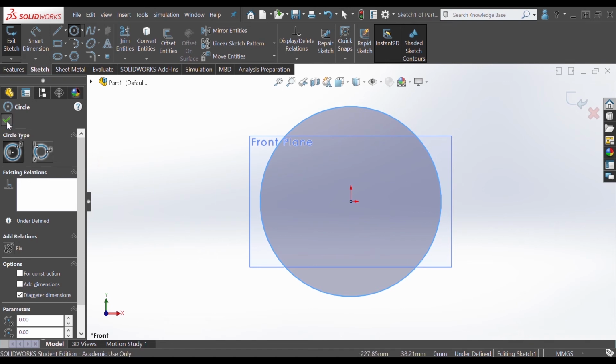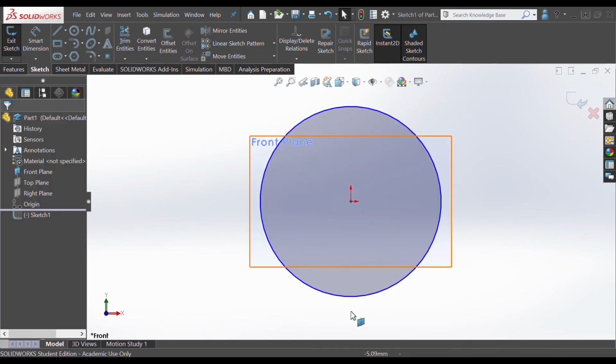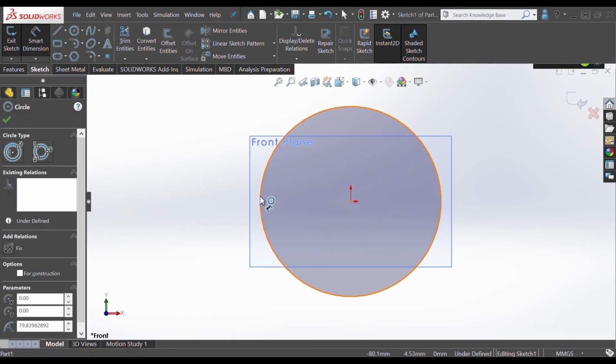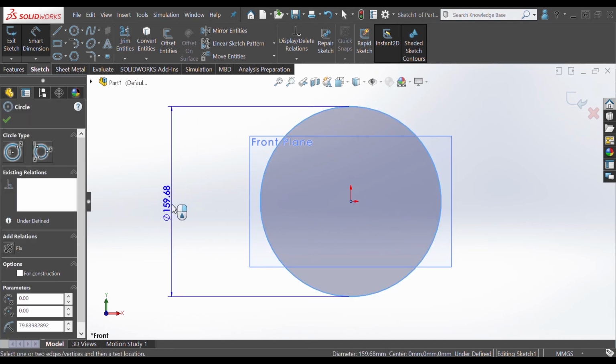Stop clicking the mouse, and then when you sketch it, you can go over here to Smart Dimension, which is a smart way to dimension the circle and give it values, dimensions and numbers. When you press on the circle, automatically it knows it is a diameter or radius. So this Smart Dimension changes, or its attributes change, depending on the figure that is drawn. So if it's a square, it's not going to give me a radius.